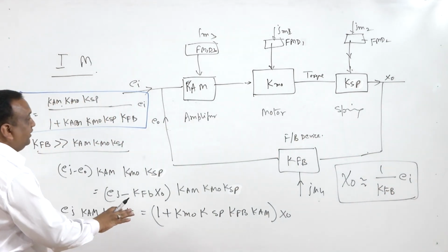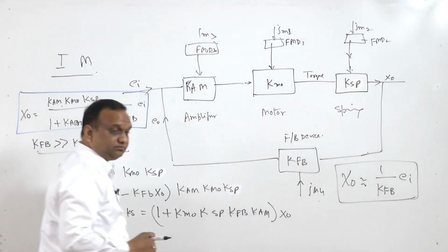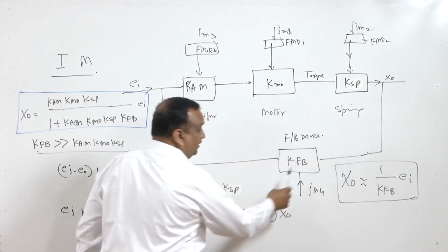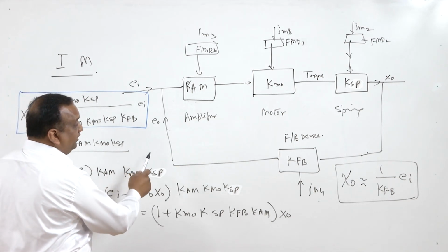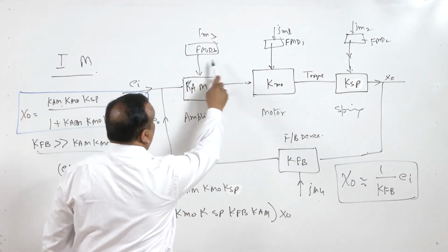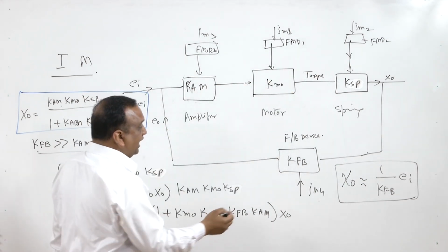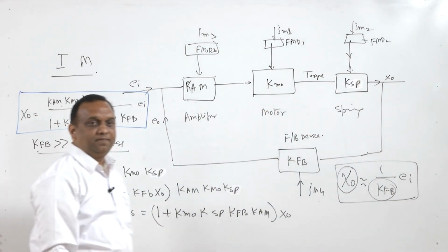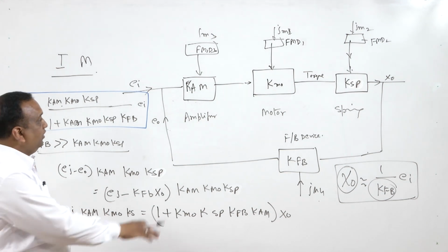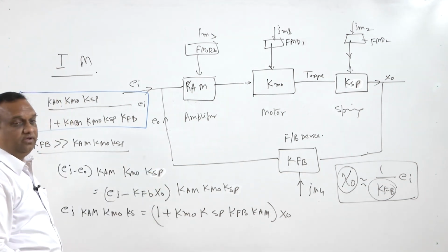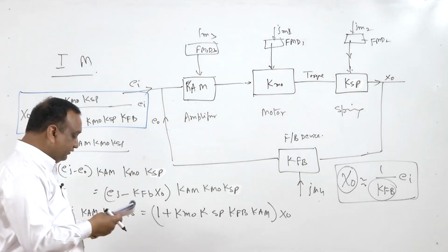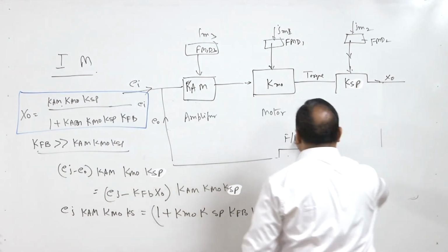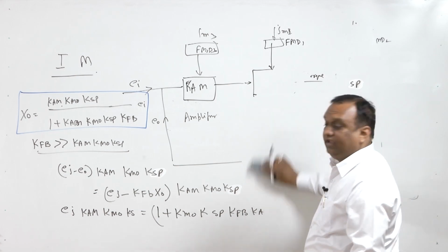Now what we have done here, we have just simply provided a feedback device, and this is high gain feedback. By using this high gain feedback, we have reduced the significance of this interfering and modifying input, and the output of the measuring instrument is dependent only on KFB, right? And this is how we can avoid the interference by spurious input to the instrument. So this is another method, high gain feedback, which can be used for avoiding the interfering and modifying input.